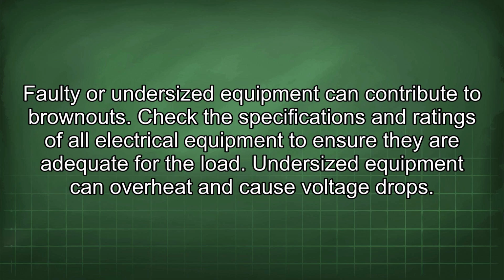Faulty or undersized equipment can contribute to brownouts. Check the specifications and ratings of all electrical equipment to ensure they are adequate for the load. Undersized equipment can overheat and cause voltage drops.